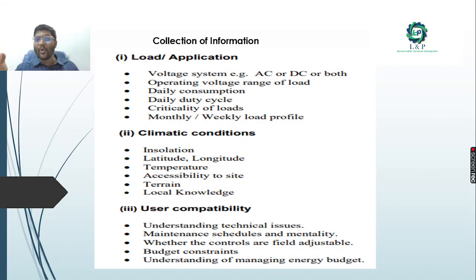You need to know what your load is, what your application is, and what your voltage system is, whether you have an AC system or a DC system. Most probably in our homes we have an AC system. What is your daily consumption, what are the critical loads, and what is your monthly or weekly load profile. Those things are very important in calculating the load.